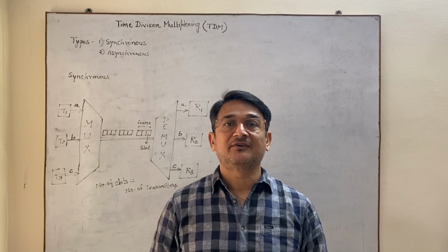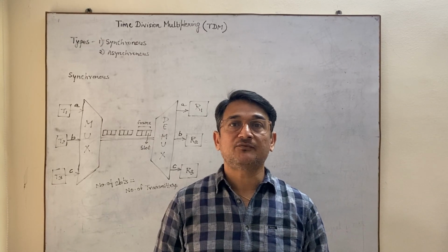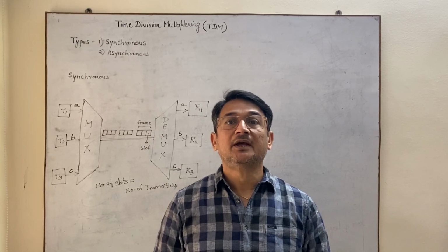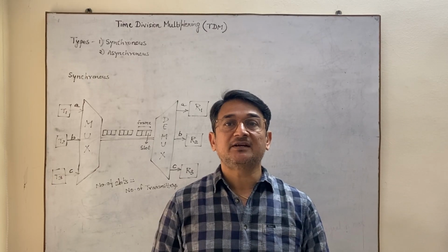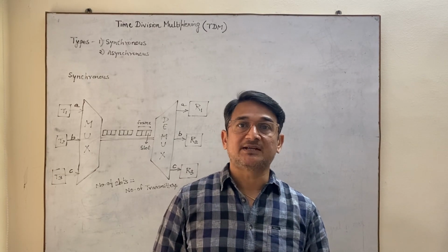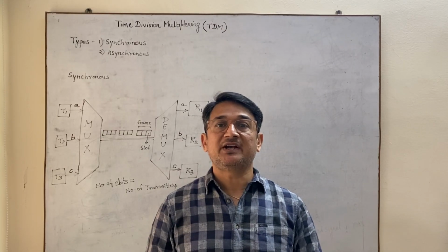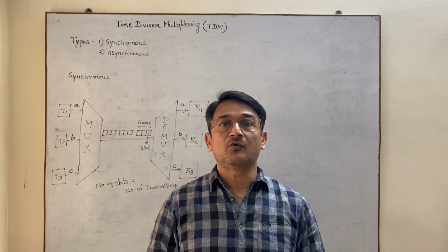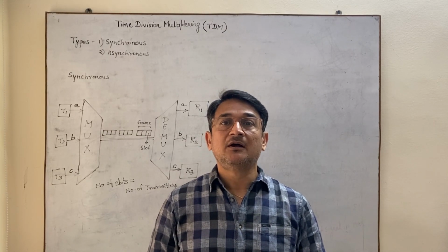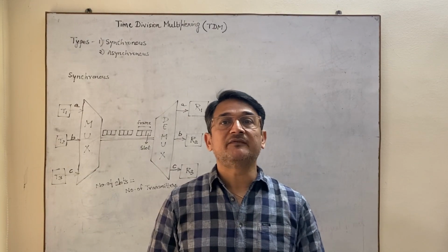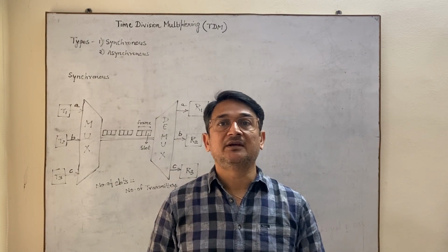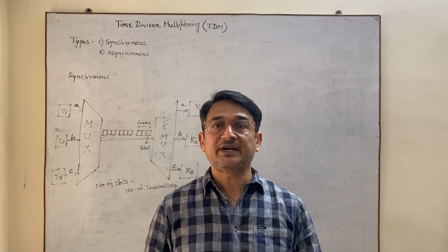In today's video, we are going to understand the concept of time division multiplexing. Before time division multiplexing, let us understand what is multiplexing. Multiplexing means simultaneous transmission of multiple signals. That means if you want to transmit more than one signal through a common channel, then we will use the process of multiplexing. The multiplexing process is of three types.